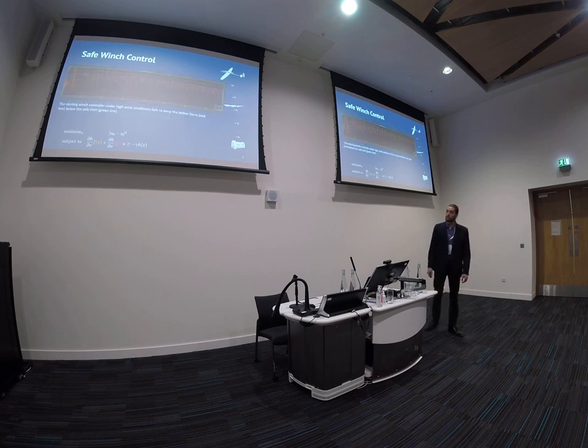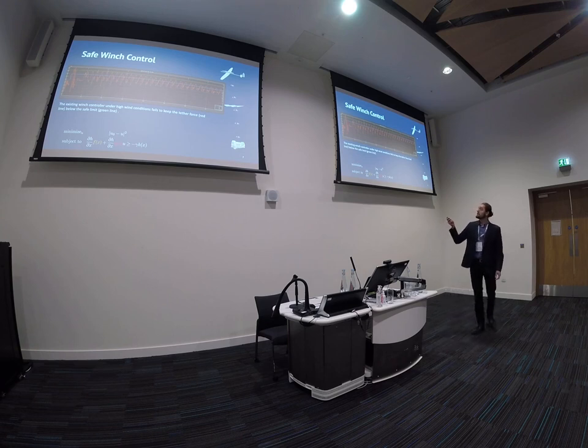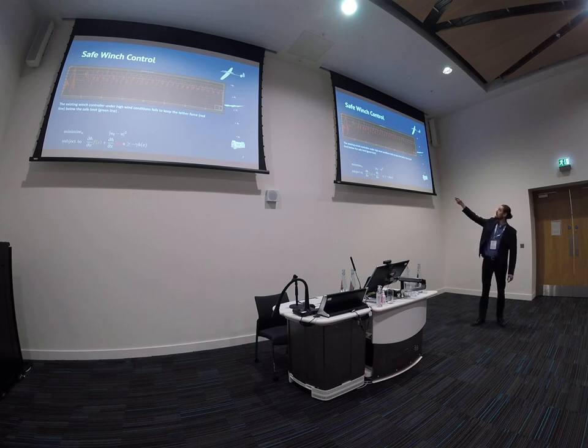And if we look at the safety properties of the winch using our baseline controller, for the winch dynamics here I used the megawatt version. I implemented a velocity tracking winch controller instead of the existing force tracking winch controller, which was left over from Sebastian's RAPS work. And we can see, I don't know if you can see this at the back, there's a green line here that tells us the maximum allowed tether force that we want. And we sadly exceed that maximum tether force. So this would mean that in practice we would be encountering quite a lot of ruptures.